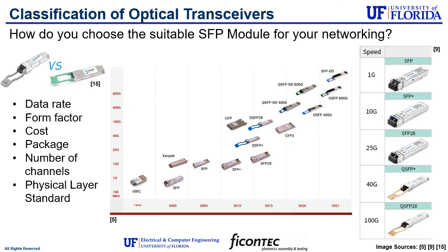Now, choosing the correct transceiver for your application all depends on the capabilities that you require. In general, most transceivers are some form of small form factor pluggable, even if they do use a co-packaged design. And the common vendors that are manufacturing transceivers include Intel, Cisco, and Dell for applications like data centers and data networking. Now, some applications are so widespread and generic that you can find the same spec device being sold by multiple different vendors. And to help standardize the market, a variety of physical layer standards, or industry standards, have been defined to classify transceivers for different operating conditions and applications.